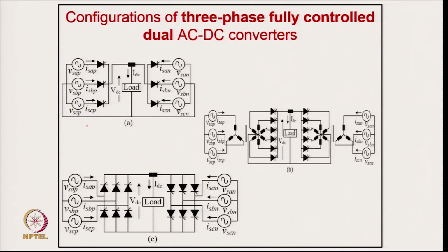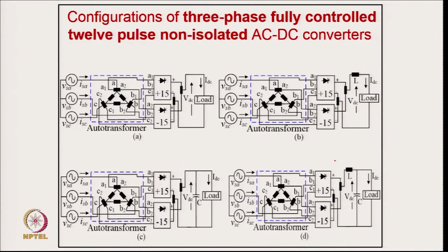And this is a dual converter. You can call it a half wave dual converter, full wave dual converter, and bridge dual converter. They also draw harmonics and reactive power from the supply, but of course the load can give 4 quadrant operation, like a DC motor drive, or you are using it for some other applications, like a 12 pulse.